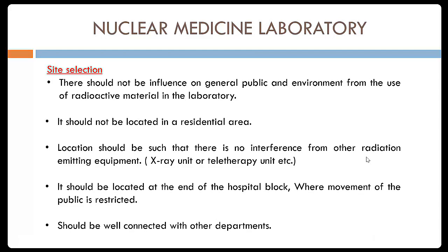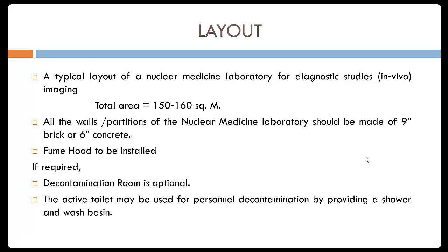And usually this nuclear medicine department should be at the end of the hospital, where the general public is less, and it should have a good connection with the other departments, like tele connection and all. Going to the layout of the nuclear medicine department, it should have a total area of 150 to 160 square meters, and the walls and the ceiling should be of around 9-inch brick or 6-inch concrete, and there should be a fume hood installed.